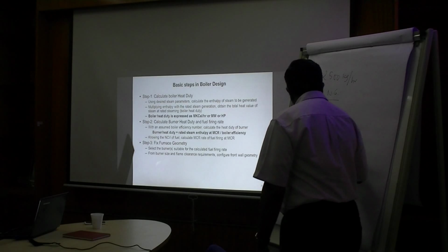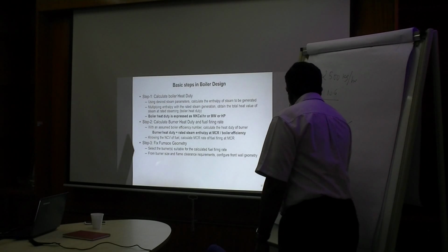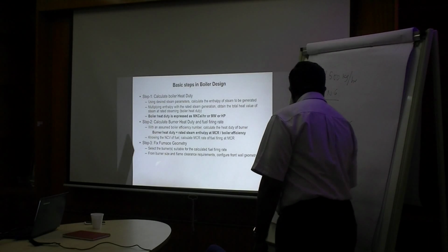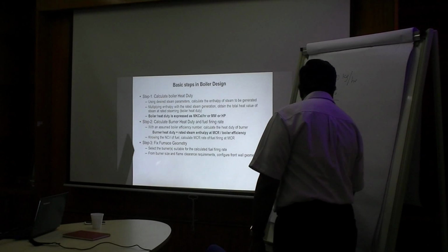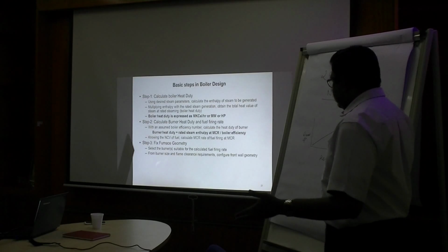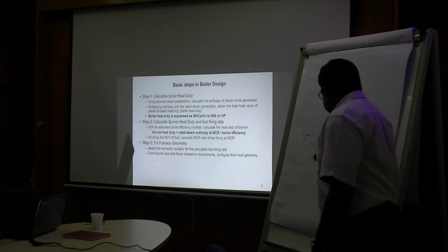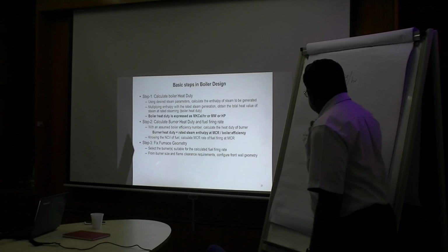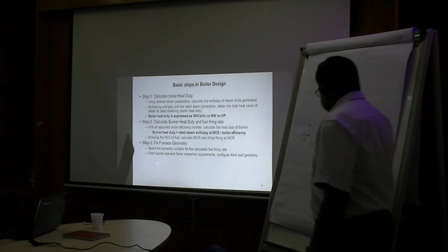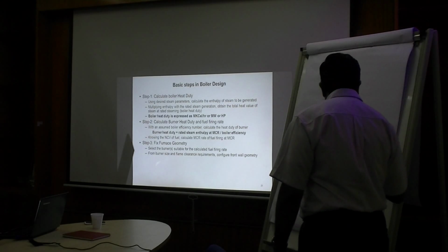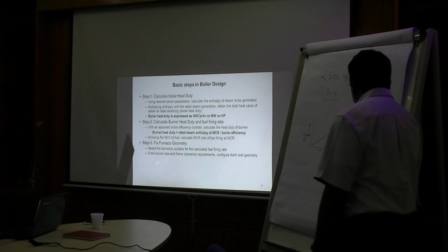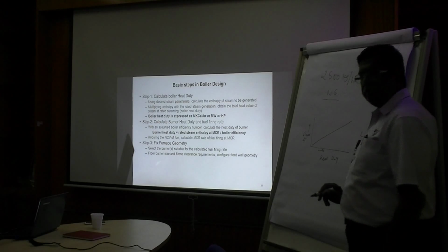Basically, that gives you the flame diameter versus heat. When the heat duty, meaning the kilograms of fuel fired, increases, the flame diameter also goes up. The flame becomes wider. Similarly, there is also a chart with a linear relation between heat duty and the length of the flame.